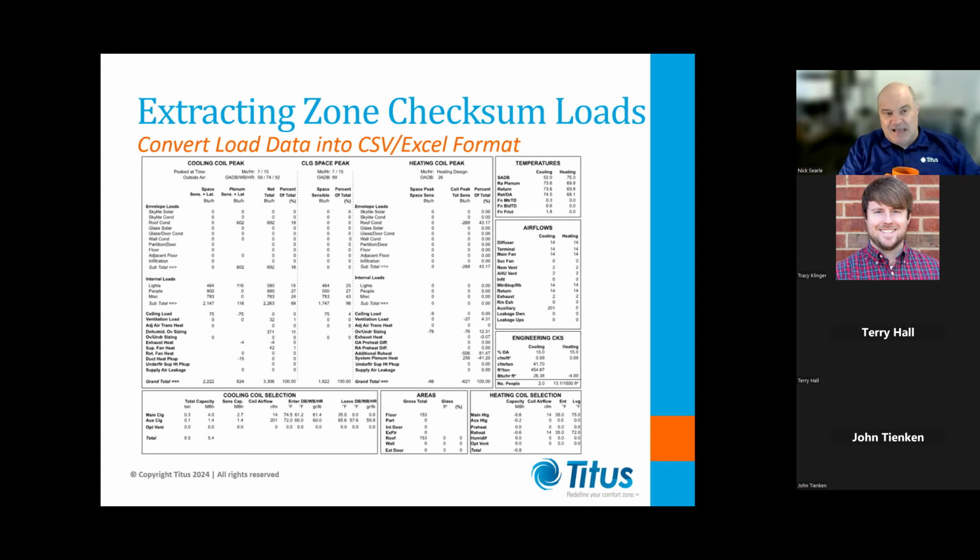Just a little tip here: when we extract the zone loads for the chill beam system design, we're interested in just zone sensible loads. So that's in that column there. And obviously your latent load, by the way, because this selection software will work out how much air you need for your dehumidification as well. That can be done with this. If you look here at your people load, you've got your net total and you've got your space sensible. So you can subtract one from the other to get your latent loads.